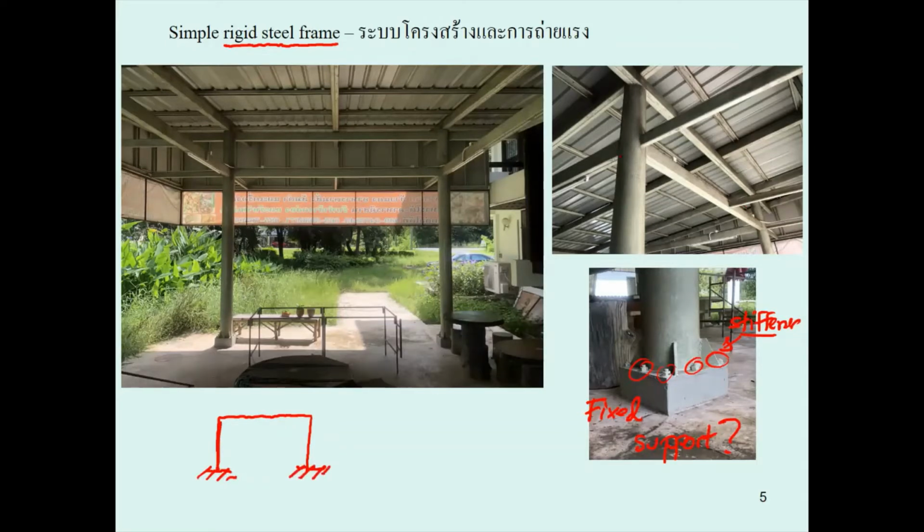And then you consider a little bit further, there are connections between the frame and this column. We call this the rigid joints, okay? And that means when you model the structure, you may put some symbol to make it a rigid joint. And you can see this is not the end of our modeling. There is another beam on top of this one, okay?